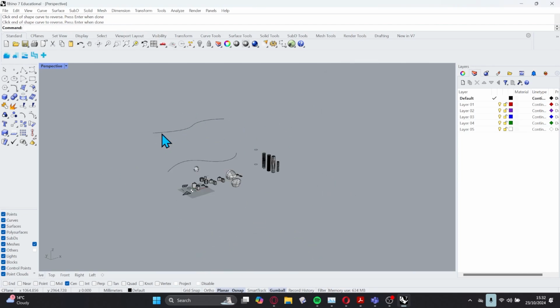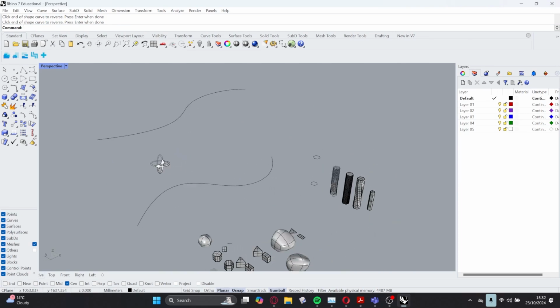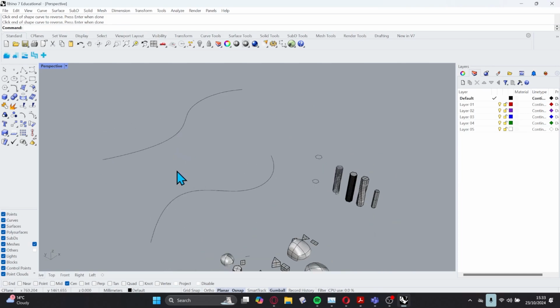But there's so many different ways that we can use the loft command. Okay? Does that answer that question? Yeah. So that's how we can begin to start to loft different surfaces. So exactly. The way that you've just done that there, that's exactly how you would do that. You can extract curves from it, and then we can begin to loft between those curves to create new geometry.